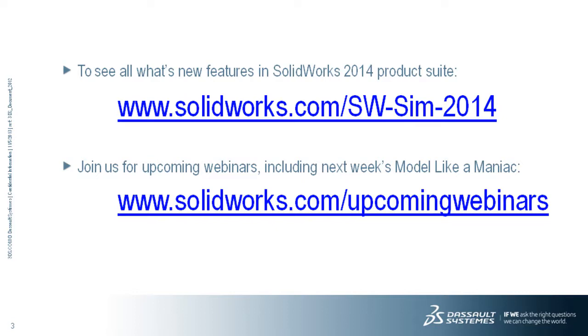In terms of package, inside SolidWorks Premium, you can test your product made of linear material, or with what we call a linear assumption. So in SolidWorks Premium, you can get the stress, the displacement, the factor of safety. The example that I used with the bicycle crank, you can do that with SolidWorks Premium. And then you can do as well what's called time-based motion, but I did not do any motion demo here because, again, it was really focused on structural analysis.